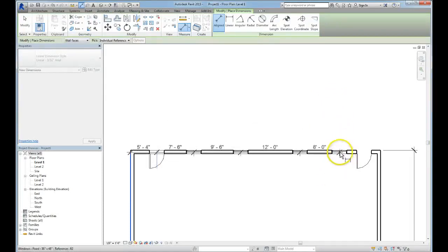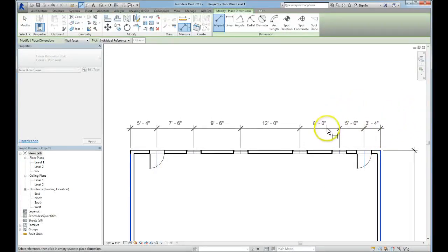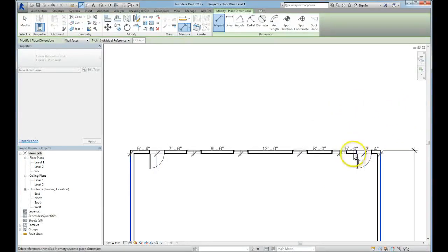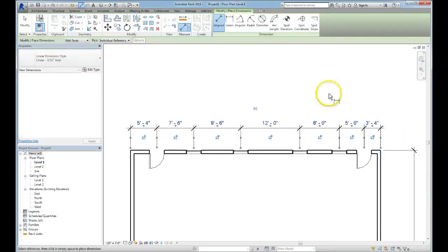Okay, and when we finish up, we click on the exterior of the other wall, and we have them all joined. Now in order to end this process, you need to click anywhere except on one of those blue snap lines. Clicking on those lines will either undo or redo one of the joins that you've made.